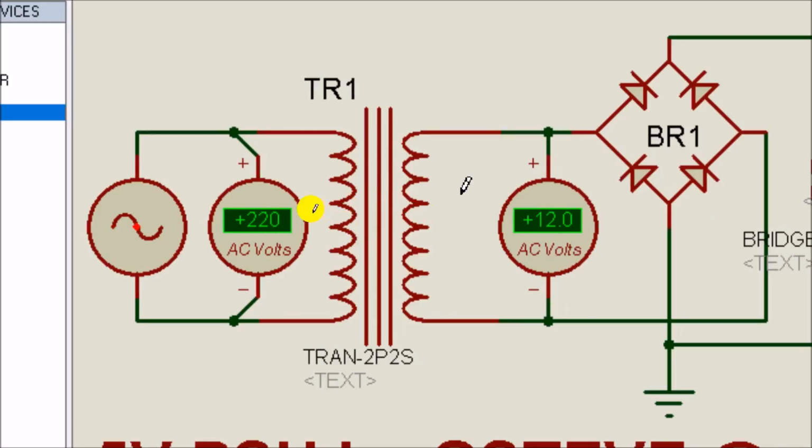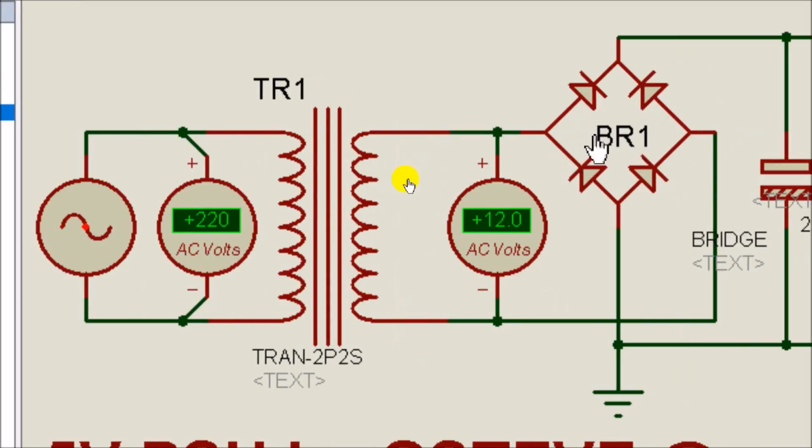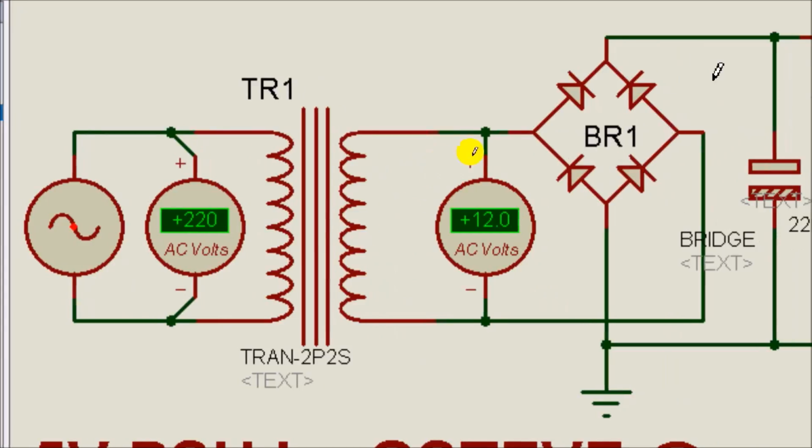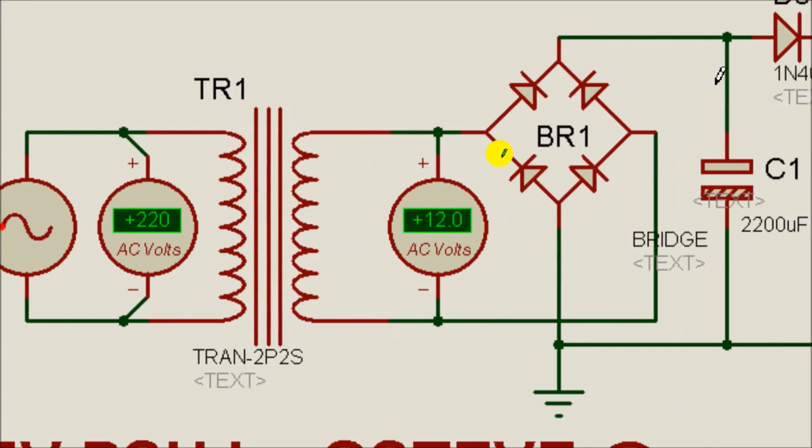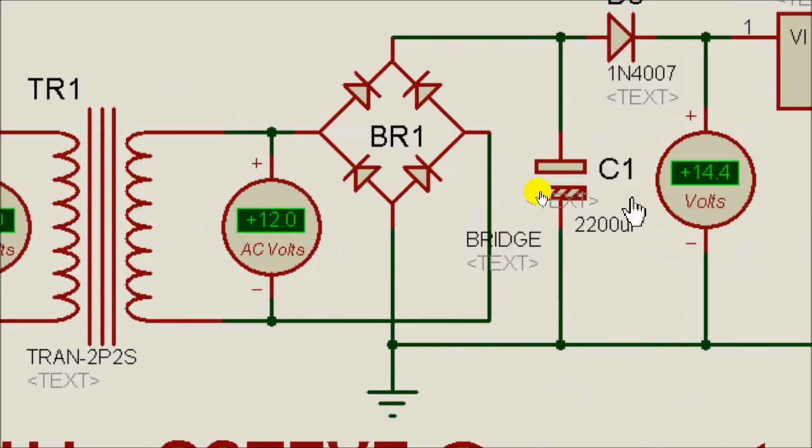So I have my AC coming in and stepped down with this step down transformer to 12 volts, and here is my rectifier. This is my full bridge rectifier. Why am I rectifying this? I'm not here teaching about PSU, but I'm going to do that now, because we're doing something very great. You need to know that I am rectifying this so that I can convert it to DC, direct voltage, and that has been done. I'm using this capacitor here to charge. It is an electrolytic capacitor, 2200 microfarad by 50 volts or 225 volts, or something greater than 12 volts. That's what you're going to use here.